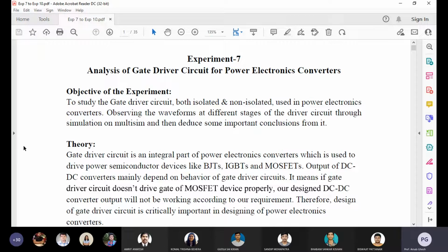Now you have to scale down the 12 volts to 2 volts. Otherwise, how would you get the voltage error? After getting the error, which is almost DC, it is passed to the compensator or controller circuit. Then you compare with a repeating sequence, so you get a PWM signal. Now that PWM is fed to the gate terminal of the control switch.